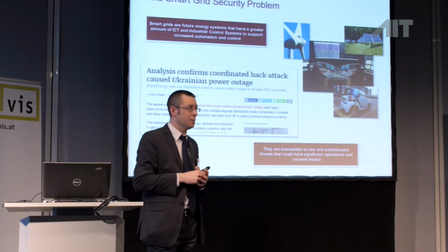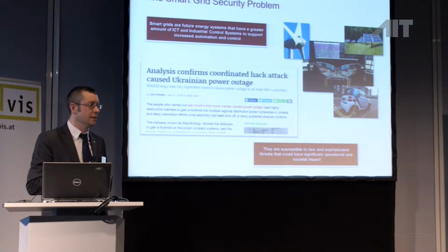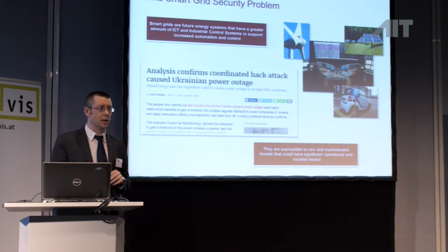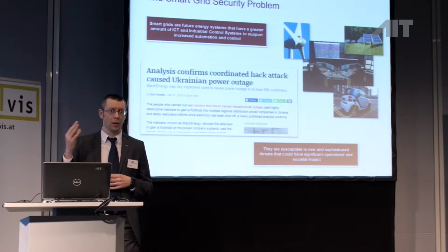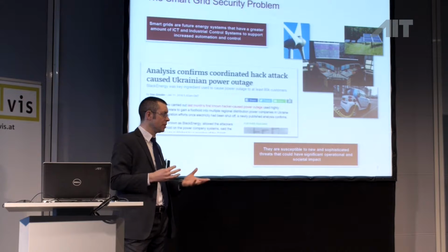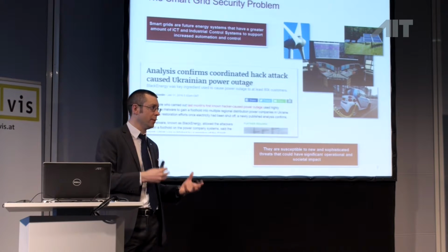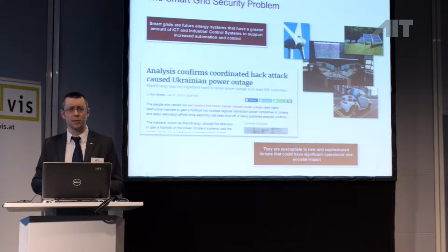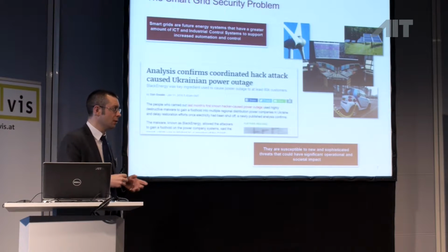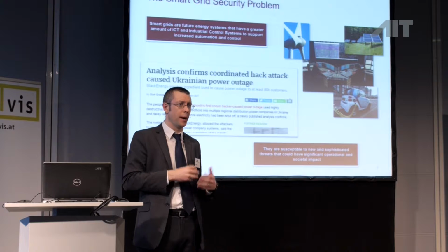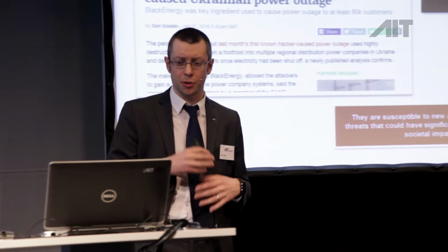I think if you were around earlier today, you heard me say this already. So we do smart grid security research. What is the smart grid? It's the future energy systems, basically, that have a larger number of renewable energy sources, such as photovoltaics, wind turbines, and so on. And they need distributed monitoring and control. And this new distributed monitoring control, which is implemented using ICT systems and SCADA systems, introduces new vulnerabilities and new threats. And some of those threats can result in physical implications to the power system, so power outages, voltage drops, frequency distortions, and so on.